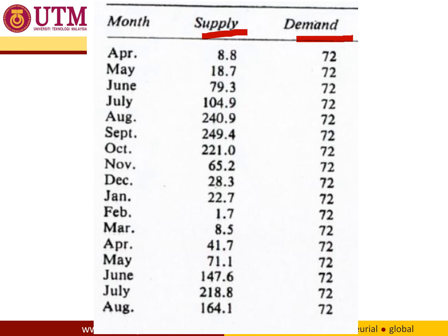How you calculate demand values is actually from the population numbers. There are ways to measure the demand. And the supply you get from the inflow, or hydrograph, going into the reservoir. So this is the data, similar to the example before, but here you don't do the mass curve.